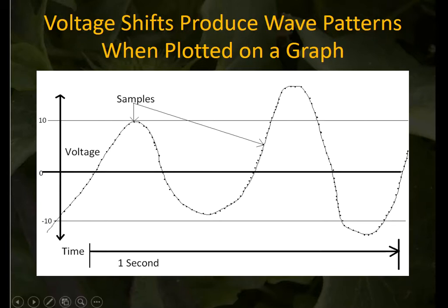So we're comparing the electrical gradient difference at moments in time, and the number of these measurements or samples is called the sample rate. For example, a typical EEG recording device currently in use would have a sample rate of approximately 200 or 256 samples per second or faster. More samples per second generally is better, and I'll show you an example of that in a bit.